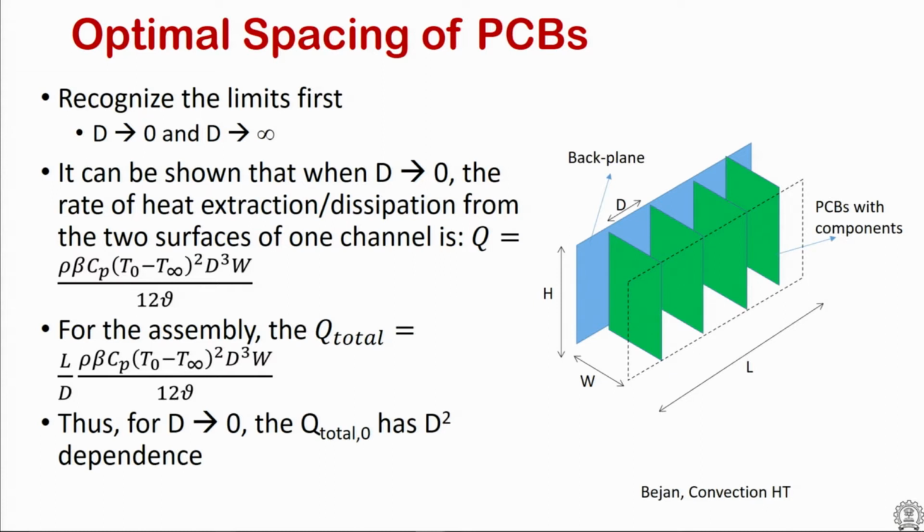And how do we arrive at this expression? It is purely talking about m Cp delta T. When you have a fully developed flow, then one can assume that the temperature difference, the non-dimensional part of the temperature difference, is quite fixed. So, using that assumption, if the plate temperature is T naught and T infinity is the temperature of the incoming fluid, then the temperature driving force is given by this.